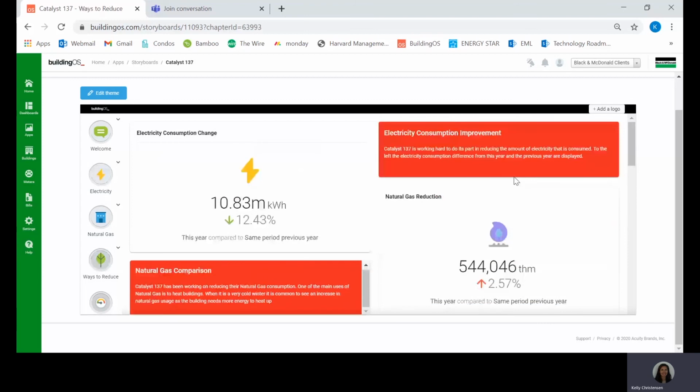So this is really just an example of what a virtual metering integration would look like. You can see the report is very similar to that of a hardware wired installation. However, we only have the information and the data available at a full building level, seeing that we are not installing any meters on any distribution panels or receptacle panels or lighting panels. We're just depending on the utility to push that full building data.